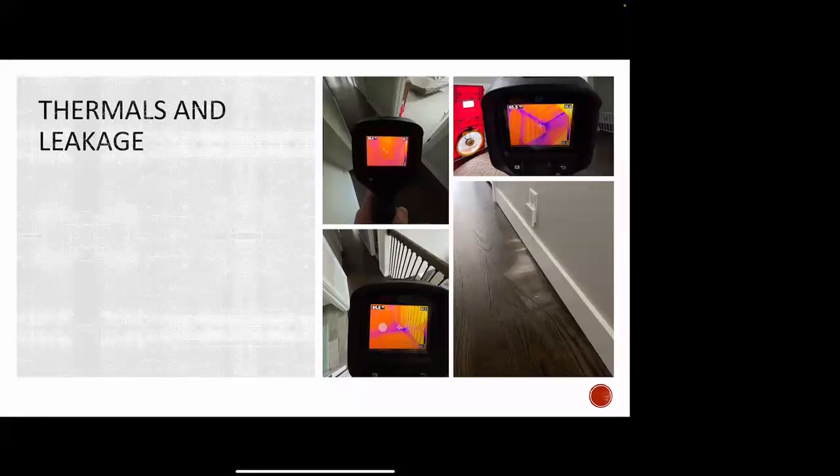So you can see here the thermal pattern on the bottom left picture of the thermal imaging camera here of the air leaks coming down on a second floor. Same thing here. And then you can see all the air leaks that we have on this new staircase that they put in. And you can see the heat actually being pulled in from the attic, facing that side of the house, the sun was facing that side. And it was afternoon, and all that heat was actually starting to transfer down into the home as well. So we suspected that the summer was a big problem. And once we showed that to them, they completely agreed and said, man, you got it spot on. And it's not even summer.